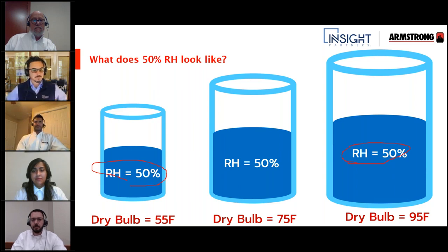Okay, next one. Can you remind me what the dot is at 75 degrees Fahrenheit and 50% relative humidity? That's for drawing your SHR line. Well, it's called an index point. That's what I call it. I don't know if people call it different things. It's where you line up your sensible heat ratio on the chart. And we get into that in part 2. That's a really good question and really important. It's a little hard to explain without actually showing it, but it's the way to draw the sensible heat ratio, which is the ratio in which air absorbs heat in the space, basically. Yep. And that's critical to sizing and selecting cooling coils. Very much so. Because if you get it wrong, you won't dehumidify.